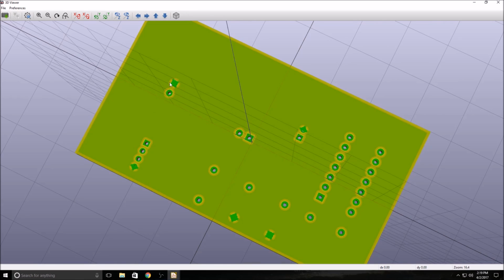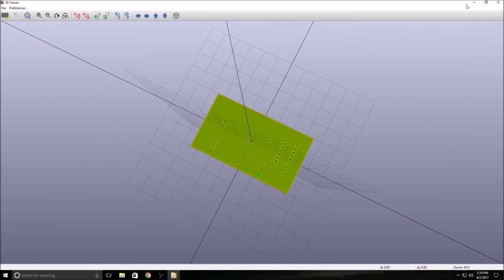Now the reason why it does it like this is to make it easier to solder on, because this is a big chunk of metal. You don't want it to be able to absorb all the heat like a heat sink, and you'll never get it up to the temperature that you need in order to solder to it. So all the pins that we designated on ground are already connected to the ground on the back. So that's pretty easy to do.